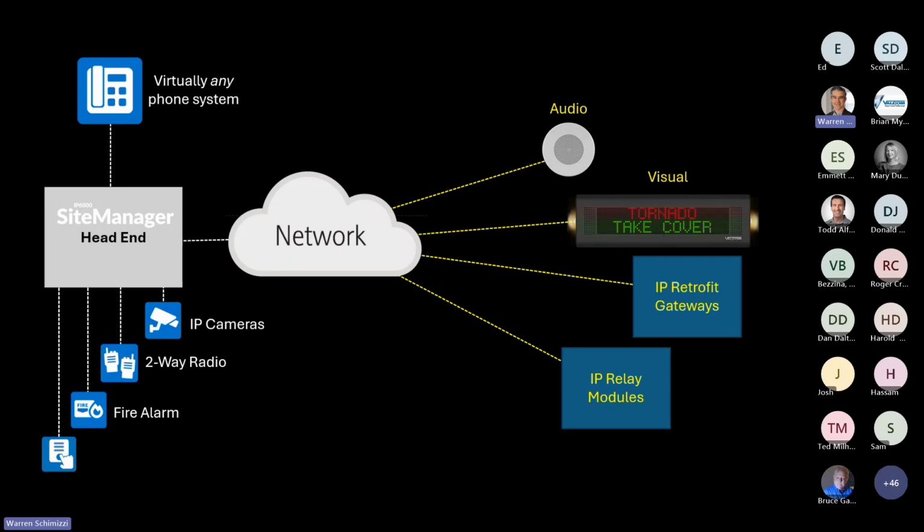So you want people to be able to get out. You don't want them to be able to come back in a certain direction where the fire is. Well, in the event of an intruder on site, you want to be able to limit that person's ability to move through a facility. So you can also, when the system is activated, release fire doors so they can only move one way within a facility by closing those fire doors.